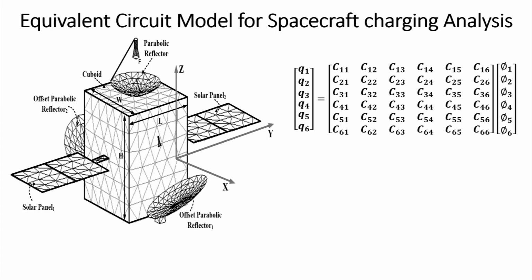You consider the different charge accumulation on different parts of the spacecraft, and then you write what we call an integral equation, where my charge is not known. So, what do we assume? We assume some known potential. If I consider a known potential, then I can find the charge, since the potential is a function of charge. This is known, and this comes in terms of integration.